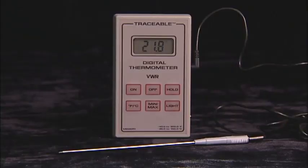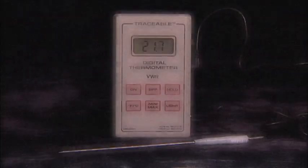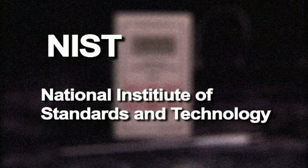The device we shall use to calibrate the sensors is a submersible thermometer. All temperature calibration devices must be NIST traceable. NIST stands for the National Institute of Standards and Technology. Purchase only those calibration devices that are NIST traceable.